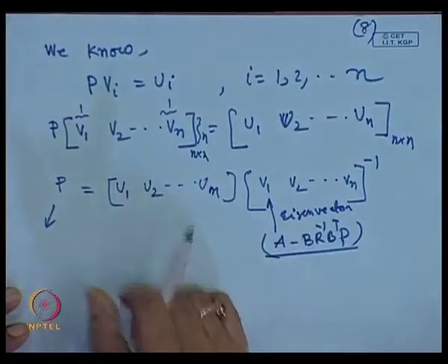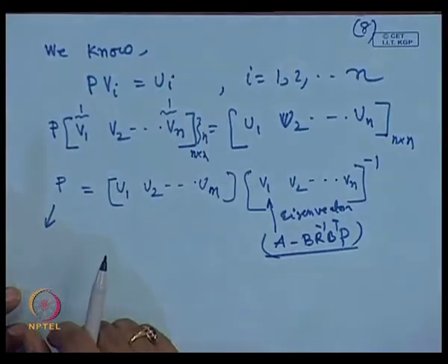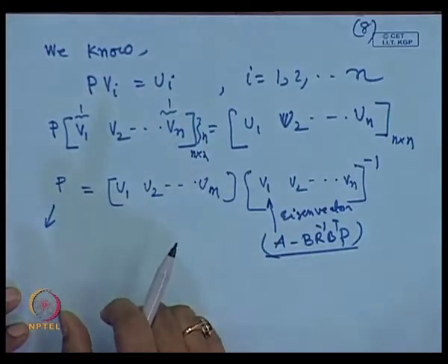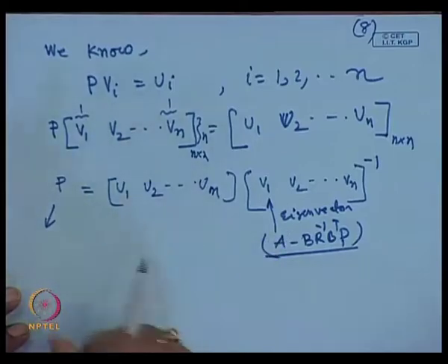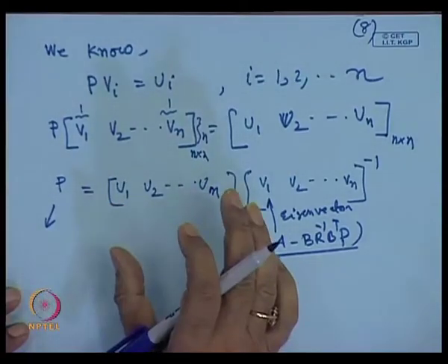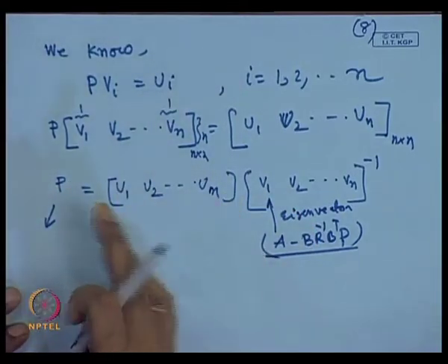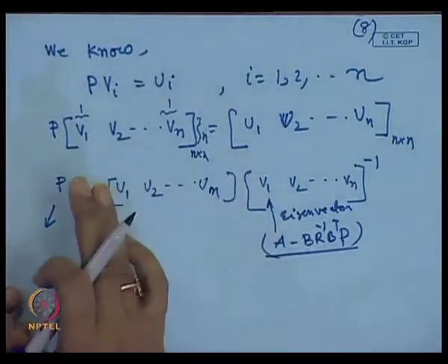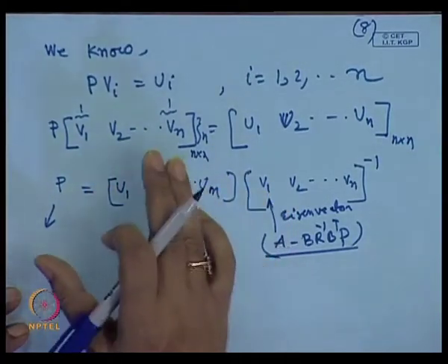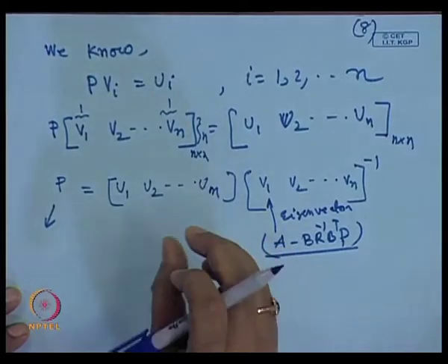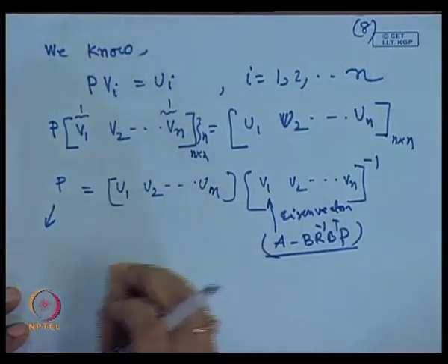The second step is that you form a Hamiltonian matrix. The Hamiltonian matrix is known to you completely, because you know A, you know B, you know Q, and you know R. Then you find the eigenvalues of this matrix and consider only the stable eigenvalues of the Hamiltonian matrix, and find the corresponding eigenvectors of the Hamiltonian matrix, agree?